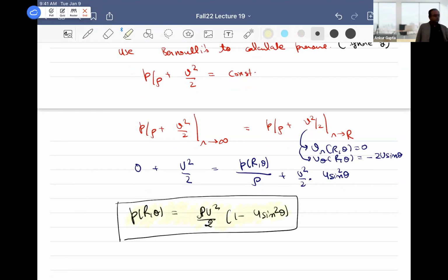Any questions? Anything that's confusing here? Right? So the process: first choose the psi or phi equation, define the velocities, then write the boundary conditions in terms of velocities, convert them into psi or phi, then propose a solution to write an ordinary differential equation, solve it, then calculate velocity, and then finally calculate pressure given Bernoulli's. And the last step is to calculate the drag, and that's why I found the pressure at the surface, because at the surface we can use the pressure.